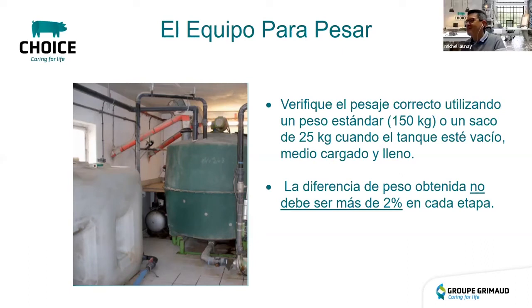I think you have specified what I wanted to say. Yes, you have to do it when the tank is empty, half loaded or full, and the difference has to be lower than 2%. So at each stage, and it's quite important.